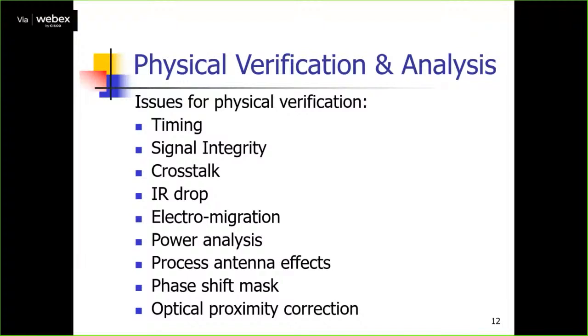The last one is physical verification and analysis. There are many issues considered for physical verification, like timing, signal integrity, crosstalk, maybe IR drop, electromigration, power analysis, process antenna effects, phase shift masking, optical proximity correction, and so on.